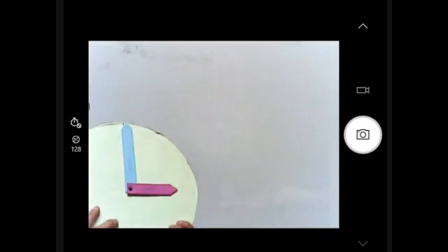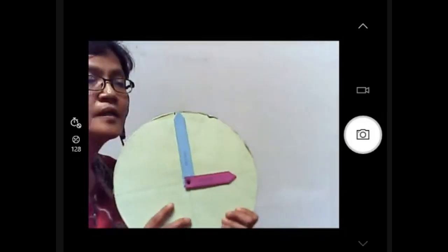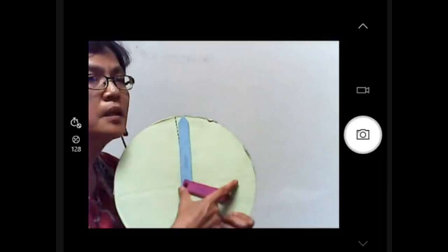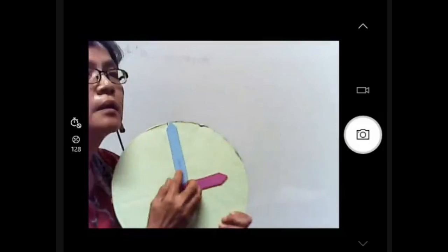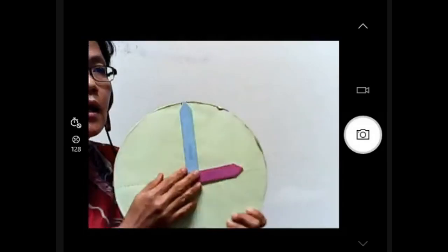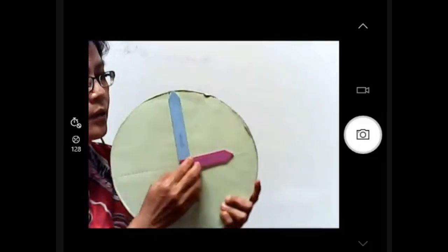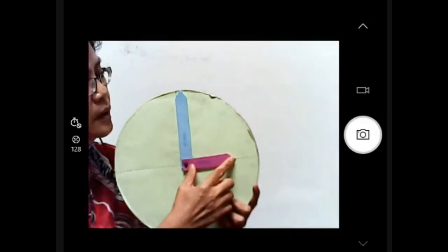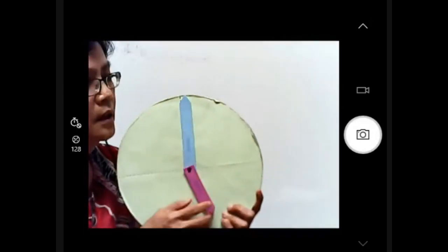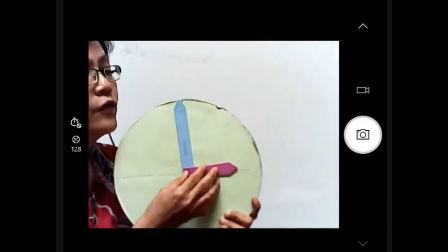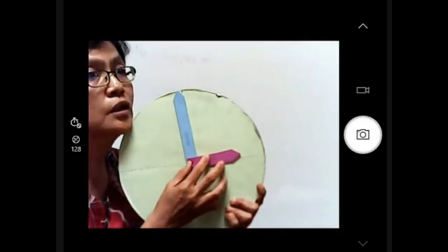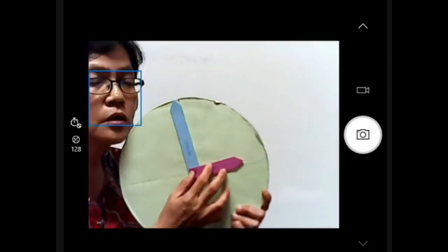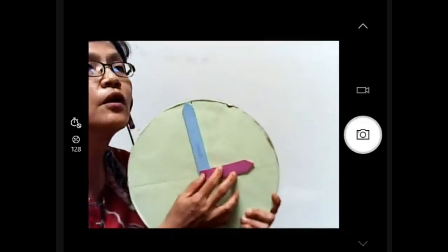So we can use it like this, meaning this is a phasor diagram kit. This will represent the current, and this will represent the voltage. At this position, I say that current is a sine graph, and voltage will be a cos graph. So from a phasor diagram, you can form a sinusoidal equation for the alternating source of voltage or alternating source of current.